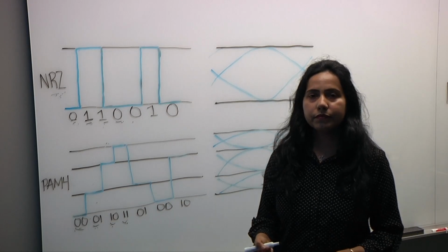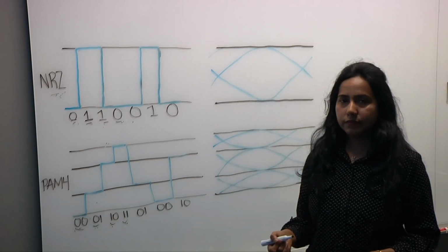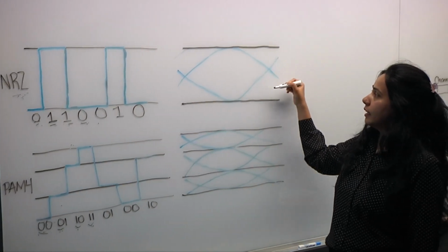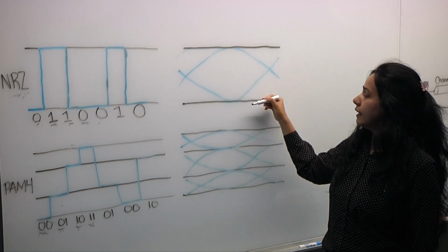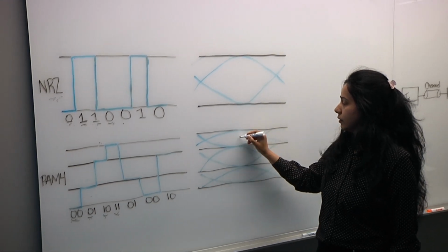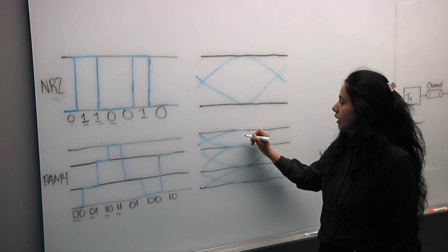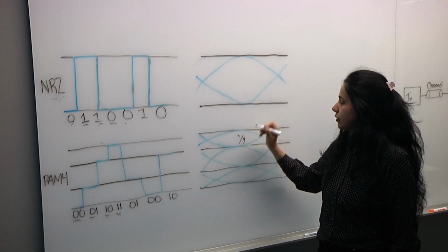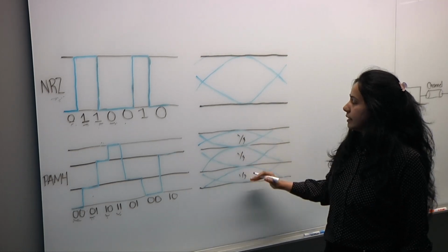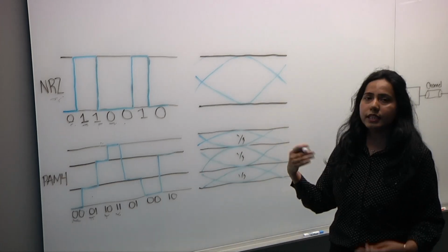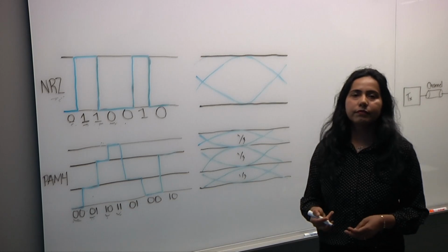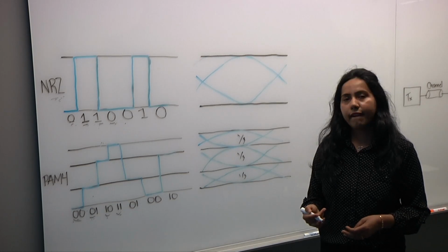How do these voltage levels translate into the eyes that most people are familiar with? Right. So for NRZ, if you see here, it was one eye, right? And then when you move to PAM4, this one eye is now distributed into 3 eyes with the same swing. So now the swing here is 1/3 of what you saw in the NRZ case. So this is all 1/3. All this is really good, like you now can transmit twice the bandwidth with the same Nyquist for Gen 6. And the whole goal here is to keep those eyes open, right? So that data can move through.